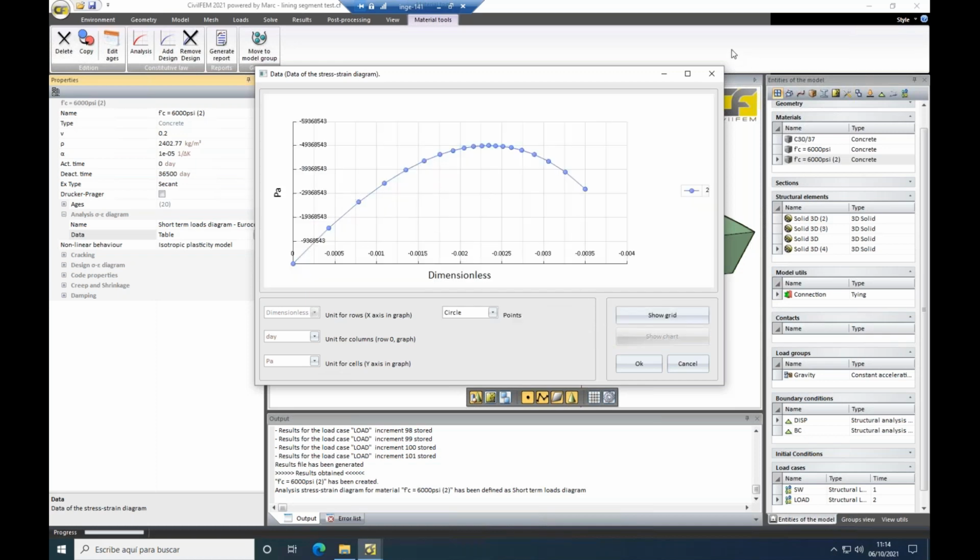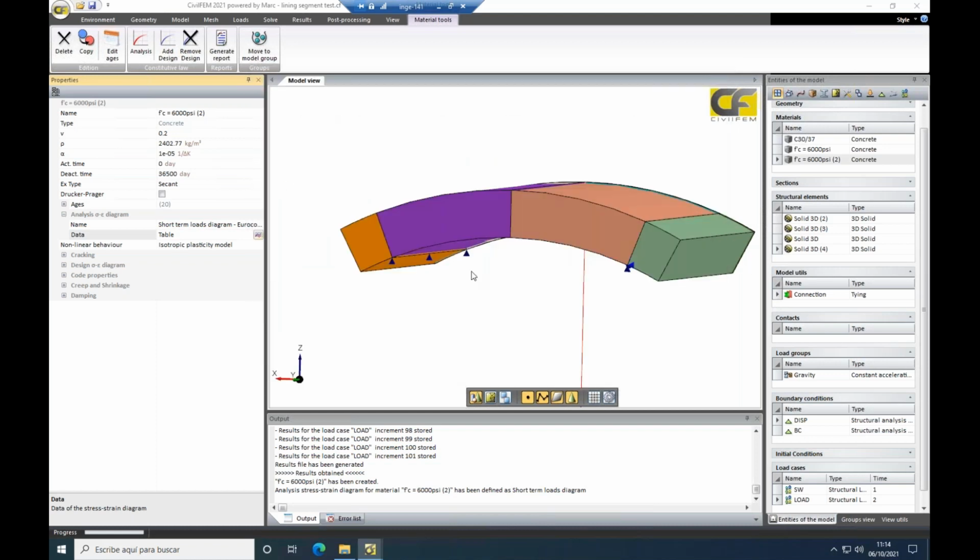After modifying this to adapt to the fiber reinforced concrete behavior, we just go to the cracking and post-cracking behavior. First, we click here to consider cracking, and first we can set the cracking stress. The cracking stress could be constant or temperature or age dependent. Temperature is for when we are analyzing a fire, an example where material properties depend on high temperatures. We could reduce crack stress, and also of course in age for early age concrete models. In this case, we are not using them, and we keep the crack stress constant because we are solving for 28 days. We are not considering evolution of these properties.